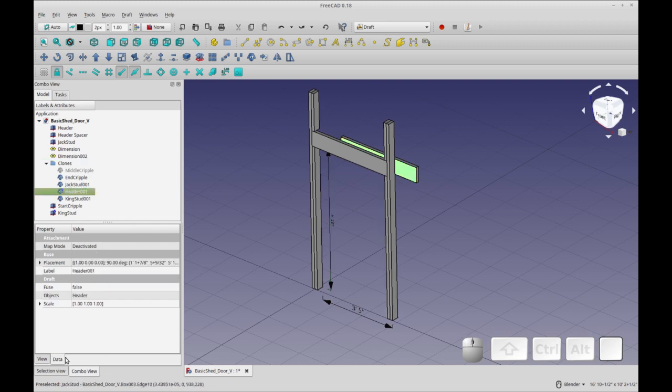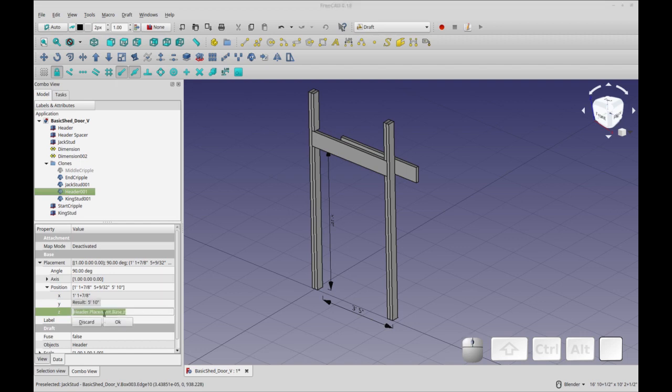I'm going to be setting this formula with parameters. I always say formulaically, that's back from Microsoft Access. So you see I've already put the base Z in. So that's header, placement, base, and Z, and that gives you the Z position of the origin of this piece, which is the bottom little corner.